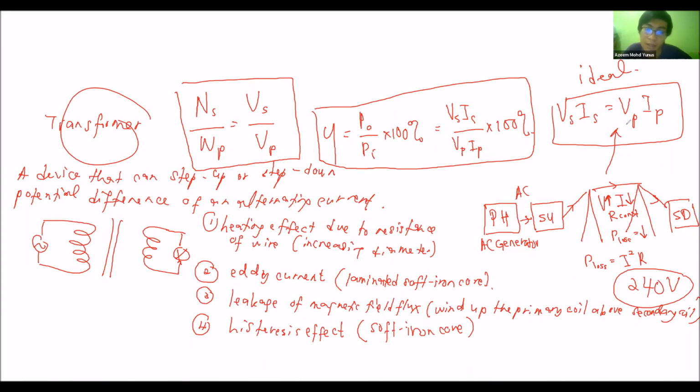So this is basically conservation of energy. The power transmitted between the transformer and the national grid network is conserved. Thus, if we change the voltage, the current is also affected. If we increase the voltage, the current is reduced. If we lower the voltage, the current is increased.